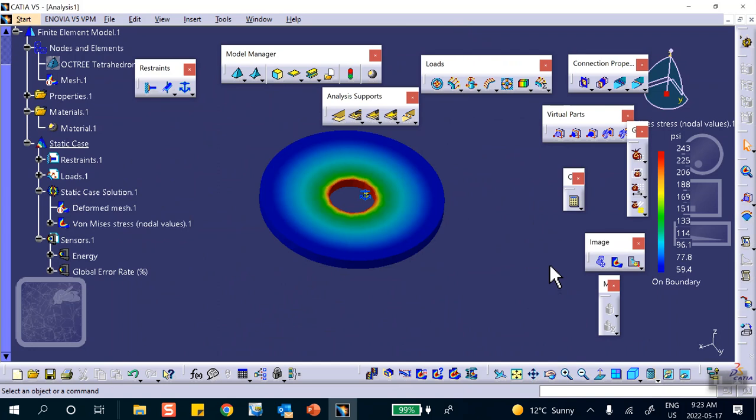This anchor or isostatic restraint is nothing but that 1, 2, 3 rule that I did for you last week. It automatically goes and applies the 1, 2, 3 rule to some nodes that you don't see. You can't see it if you want. You can find it, but it is exactly the same thing, but it does it for you automatically.